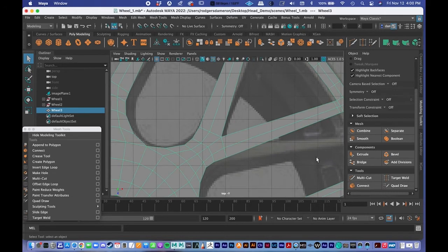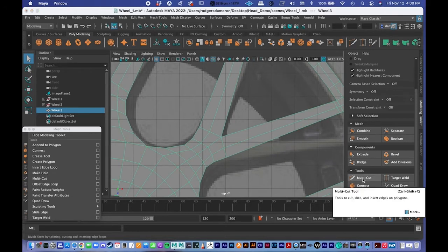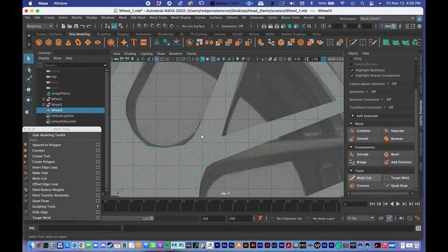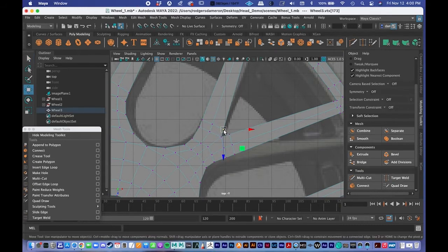So you can just use the multi-cut tool here. So in object mode, right click object mode, I'm going to press the multi-cut tool, and then hold down Control, and then just 1, 2, press Q, right click in Vertex, and here I'll just shape them a little bit.